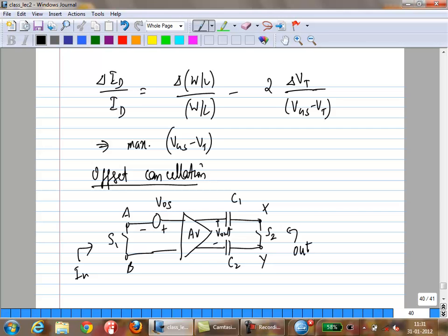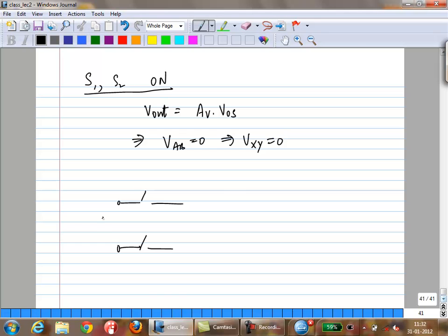You're assuming, see, the idea is if your input is differential, if you take a real amplifier, because of offset, the output has a dependence on these cross terms. Because of that, you won't get ideal common mode to be 0 and so on. That is the case you're trying to solve. The question about what happens when input has different common modes between the two differential cases, that's a whole different issue. So you'll need this. These are A and B.